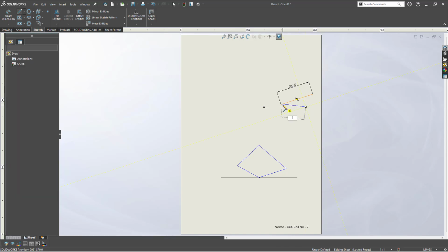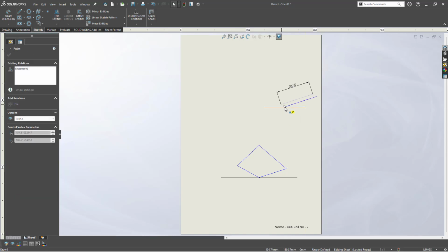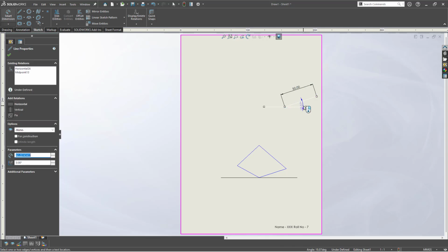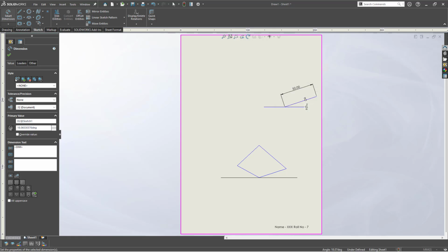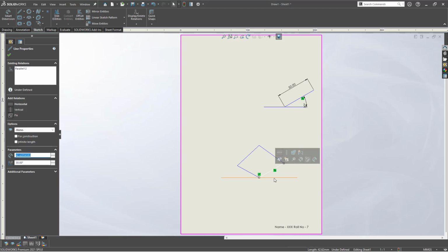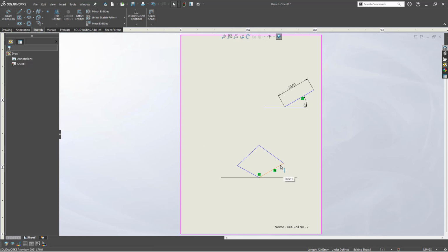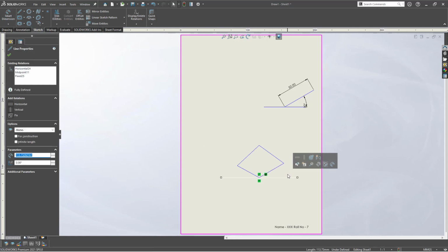and let me drag and drop it here, and you can define the dimension manually like this. The isometric angle is 30, and you do the same thing, but this is the shortest way. I'll show you what to do with this. Now you can activate the dimension. D is a shortcut to activate that. Here, smart dimension, and then just select this one and this one.